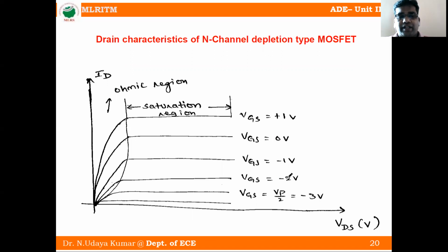The negative charge of electrons are minority carriers, because the substrate is a p-type substrate where holes are the majority charge carriers. Electrons, the minority carriers in the p-type substrate, form an inversion layer as the gate terminal voltage is positive.